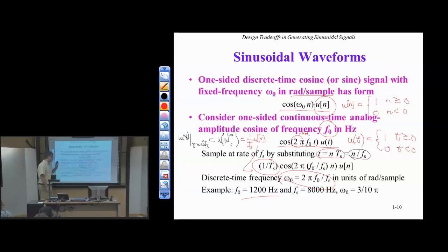In this particular case, for Lab 2, we're going to compute this cosine as a 32-bit float. We want to convert it to a 16-bit int. The cosine has values between -1 and 1 in amplitude. With a gain of 1, the cosine is between -1 and 1 inclusive, right? If you directly typecast that floating point value to a 16-bit signed integer, what possible outcomes do you get? You get -1, 0, and 1. Only 3 possible values.